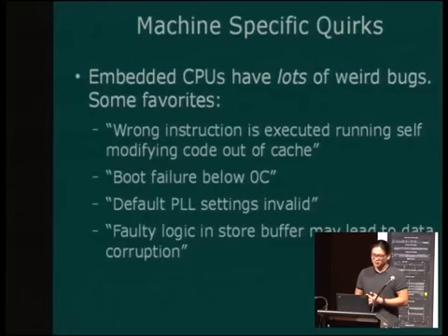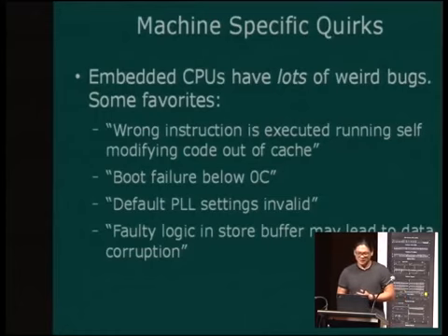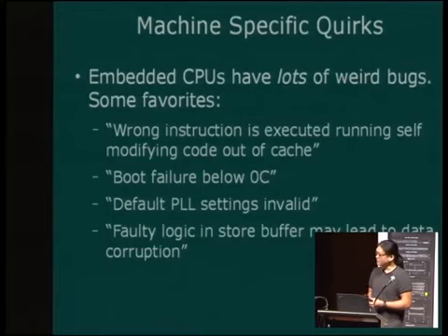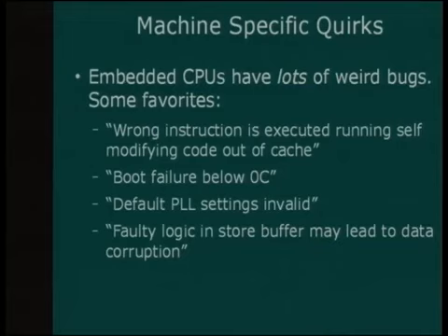These kinds of things are incredibly hard to figure out. It's very subtle, and eventually we figured that out and had to put a fix in the bootloader to correct the PLL settings. Or another one here: faulty logic in the store buffer may lead to data corruption. Again, no good. The fix to this one was again in the bootloader, where we had to turn off store buffer optimization. So a lot of these really bizarre quirks make porting to a particular product rather difficult.